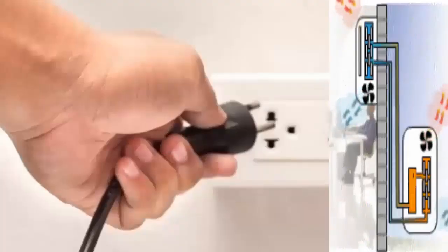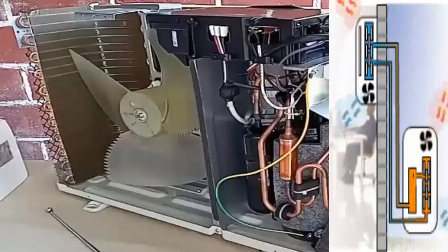1. Disconnect the equipment for several minutes, and turn it back on to check if the problem persists. 2. If the problem persists, focus the diagnosis on the external unit located outside the conditioned space. 3. Locate the sensor according to the error code, and visually inspect to ensure it is securely placed at the measurement point, and not loose.